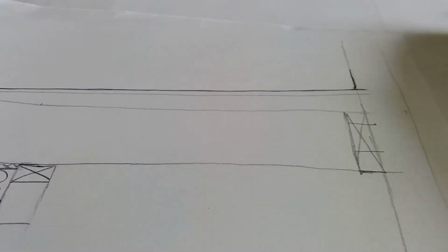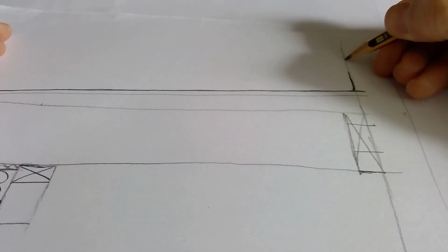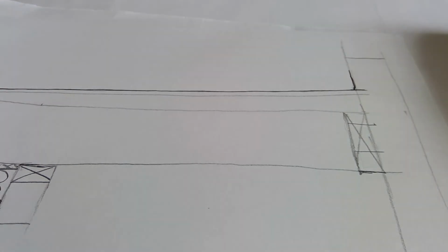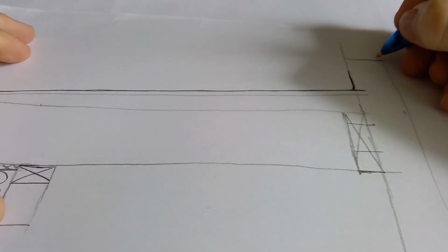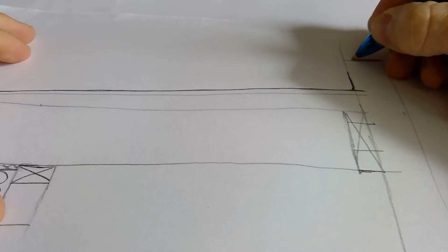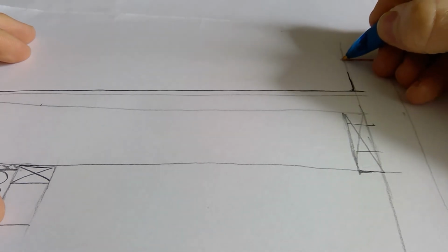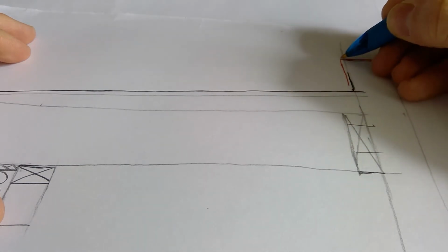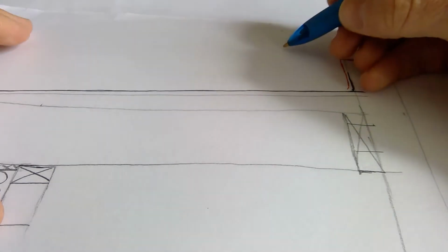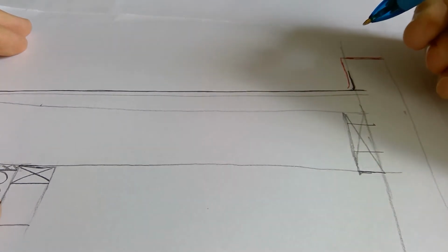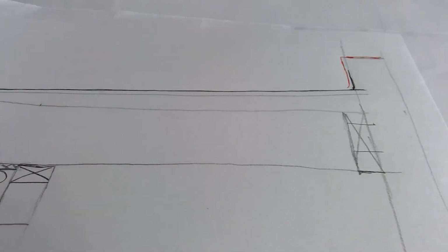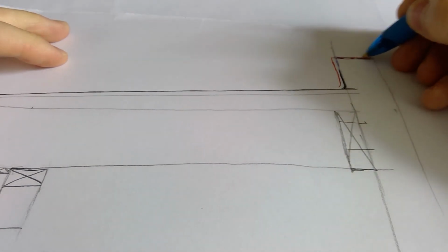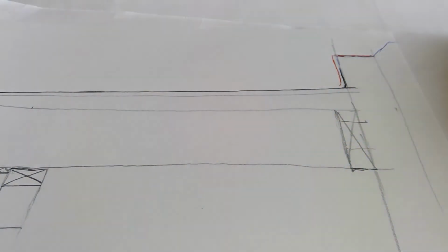Alright, now the next block above the roof, let's say it's there, we have what's called lead flashing, which I've shown before, and the lead flashing is fixed in to that joint in the block, and it comes down and wraps down over the felt. So between the felt coming up there and the flashing wrapping down over it like that, water cannot get in to that area, so that helps avoid that problem. You would also have some DPC which would run up along there as well, across and up over to the next side of the wall, which you'll see in the solution shortly.